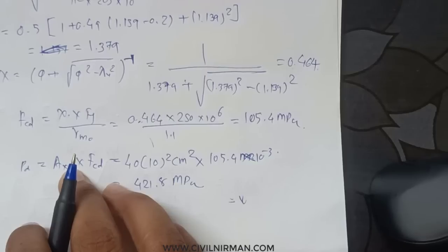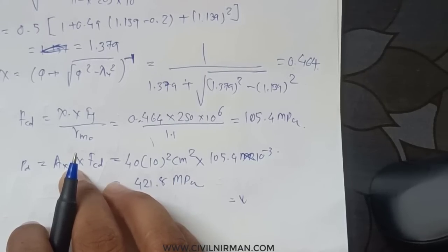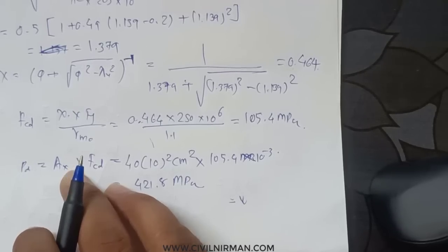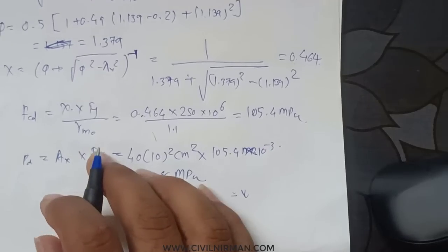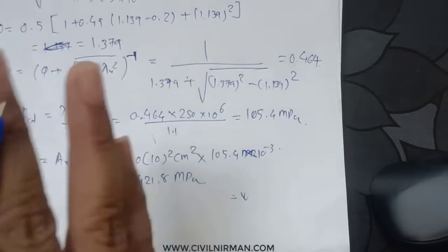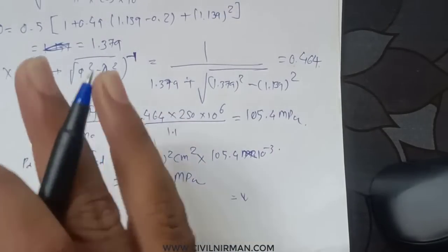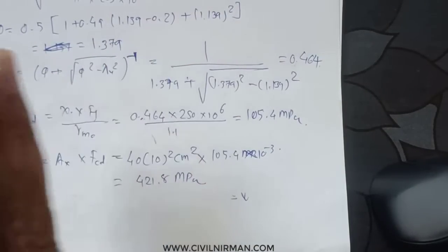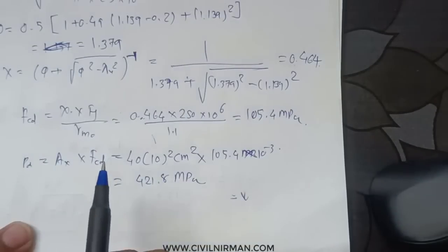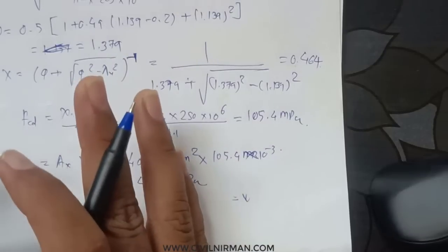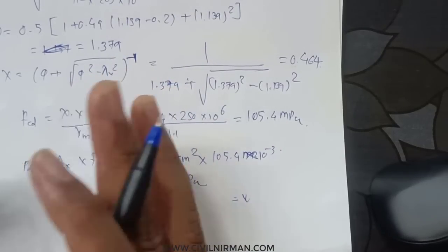And now we will check for axial compression against the flexural torsional buckling. So see, since the member being designed is an angle loaded through one leg, okay, that's the assumption that we have made, the axial compression capacity with respect to the flexural torsional buckling must be checked, that you need to work out. Okay, and the end connections, we are assuming that a minimum of 2 bolts is required, right?